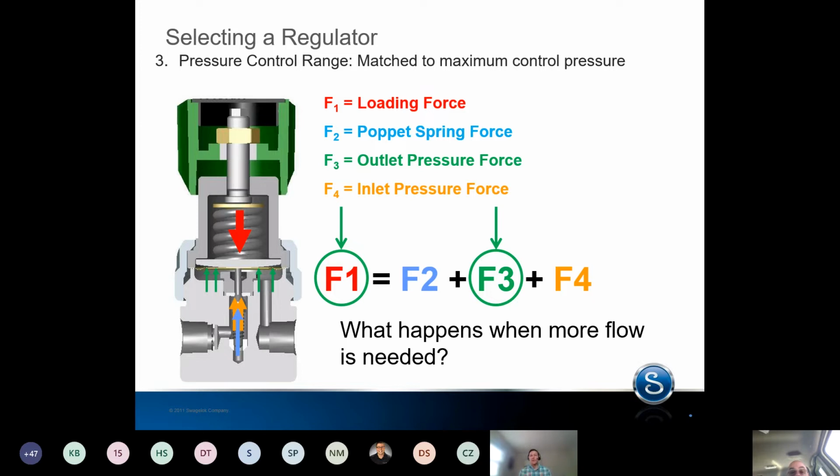With pressure regulators, you actually can select and should select that lower pressure range. So pressure regulators are quite happy to work at the upper end of their control range, and you will see better droop performance, better set point resolution, right? So every turn of the handle is actually going to give you less change in pressure, so you can more accurately dial in what's needed.